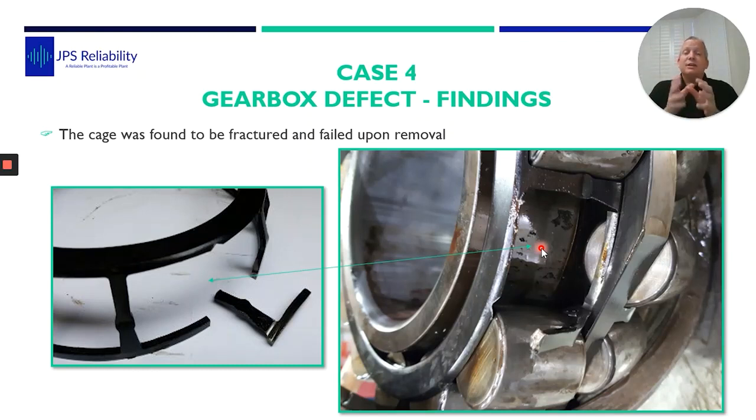So this shows you that if you know your system and you're monitoring the correct parameters, be it velocity, acceleration, displacement, some bearing condition unit, PeakVue, SPM, HDS, lots of technologies, and sampling correctly, you will see the defect. Often I hear people say, oh, vibration analysis is no good, it didn't find a defect.